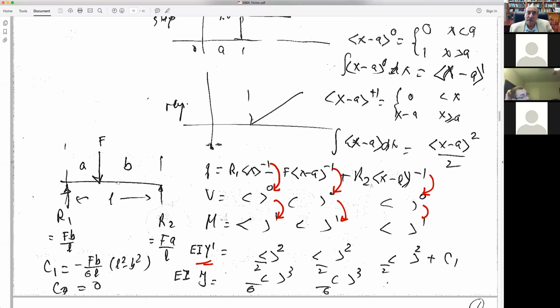And therefore, the deflection method becomes useful because it can convert the problem to finding that reaction by knowing the deflection at a point. So you know the deflection at this point to be zero, or it could even be not zero. Let's say I have a constraint that is a little bit below, not exactly at the beam, but just slightly below. If I know this gap, then the beam is going to deflect up to this point and then stop there.